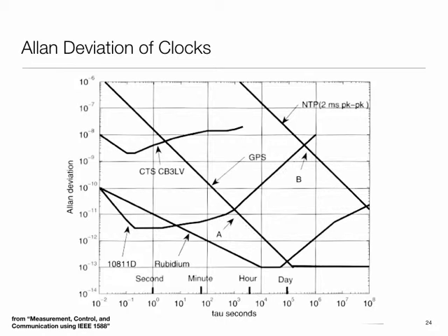So what NTP does is there is a piece of software running on your computer which is talking to these servers, and then it applies correction factors to the time. So it doesn't actually change the clock frequency of your oscillator because that's pretty tricky, although it could be done. But instead, it maintains a set of coefficients. And so the idea is that the counter, which is being driven by your local clock, the local crystal oscillator, we apply some sort of a transformation to it. We multiply it by some factor and add some offset. And those coefficients are the ones which NTP learns and maintains.